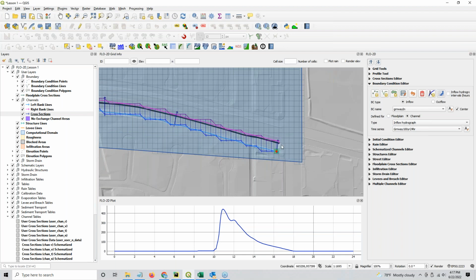And then yeah, just add a 1/2 foot to all of these cross sections just so that the water has to flow away from that inlet inflow node. Remember, inflow nodes are sacrificial nodes, okay? So you put them in locations where you can do a little bit of sacrificial stuff to them, like raise them up a little bit to get the water to flow away from it.